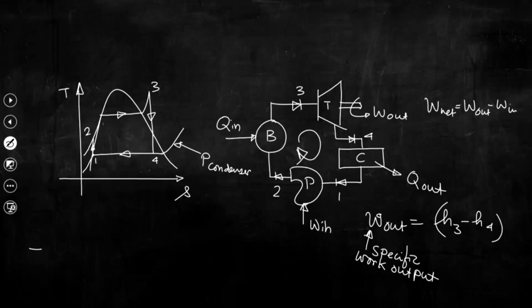So, basically we can understand that if we do not have this particular unit, the condenser, and by any means we try to condense the steam at atmospheric pressure, then the saturated liquid available at the inlet of the pump will be at a high temperature. Liquid with that high temperature will create a few problematic issues in running the pump in the long run.